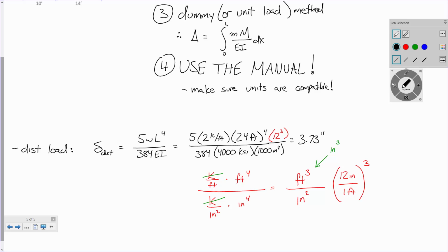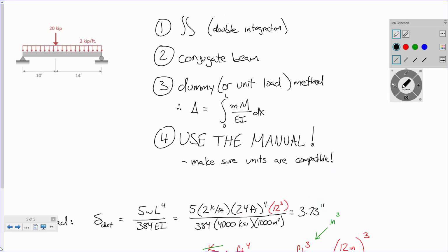Two things. One, we have to use the elastic curve equation on the very right. The reason why is because this deflection in the center is only going to give me the deflection right here. Let me pull up the screen for the screencast. So that V at x equals A is only going to give me the deflection right there. I'm not after the deflection right here. I'm after the deflection at midspan. So it's at a different point. So because of that, you have to use the elastic curve.